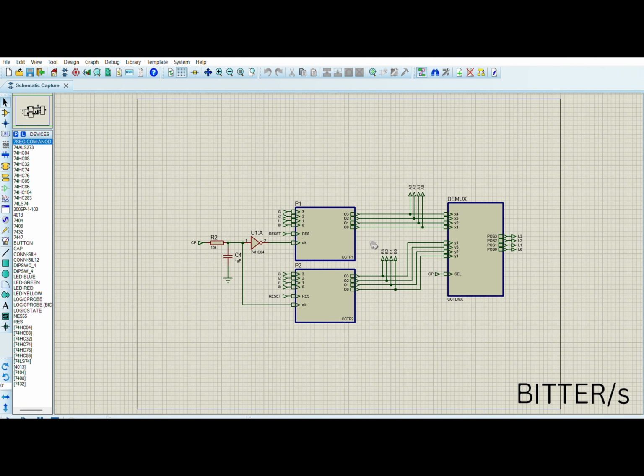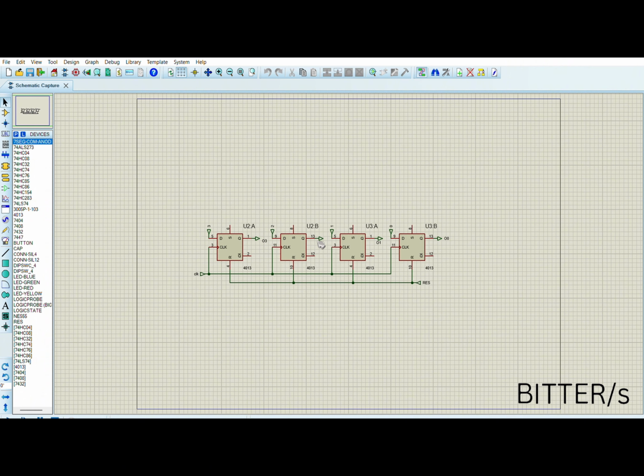The clocking mechanism of the memory module uses the player selector signal from the dice module instead of the usual high frequency memory clock. The NOT gate ensures that the memory unit of the active player is activated and the other is deactivated. After the dice button is released, the flip-flops in the active memory are triggered and the position of the current player gets updated.